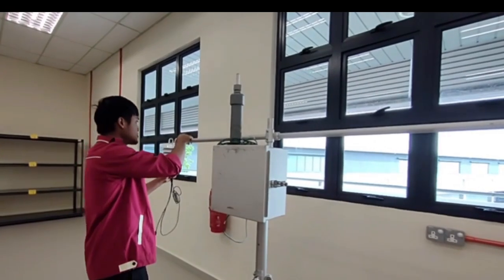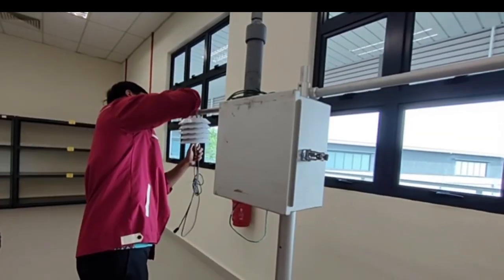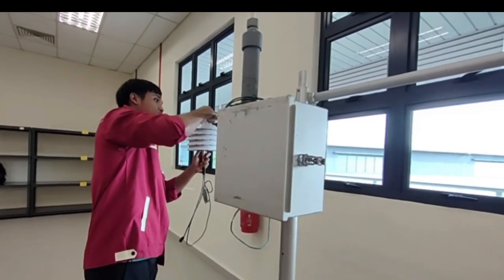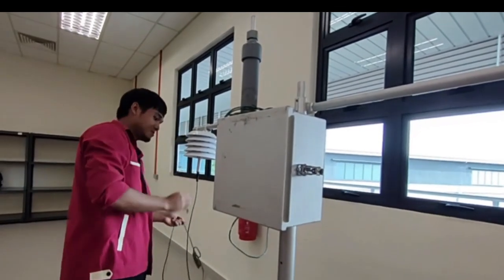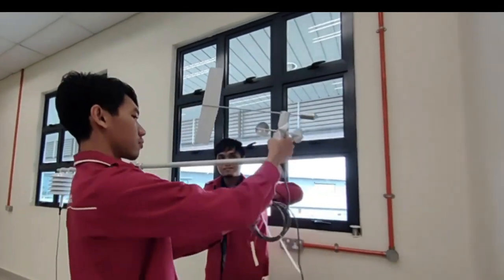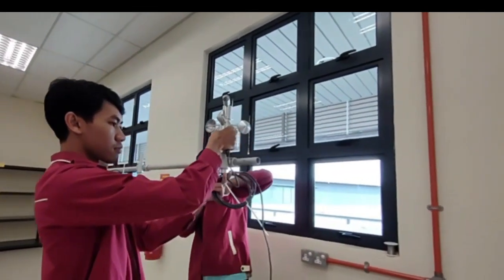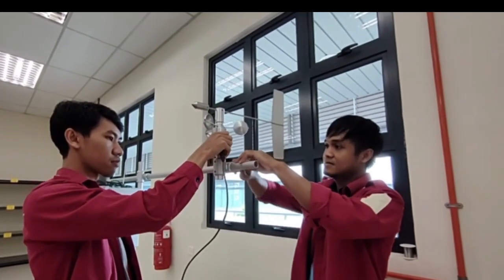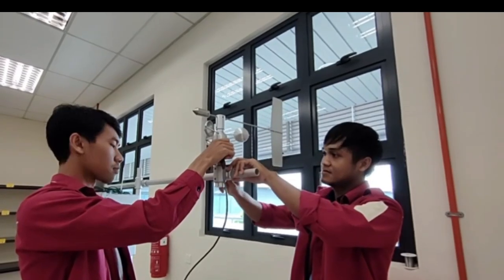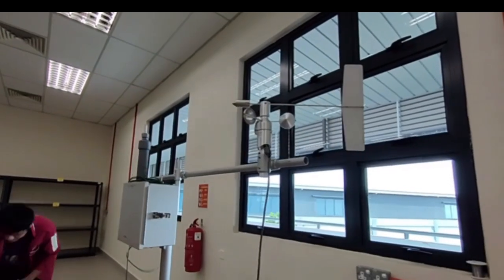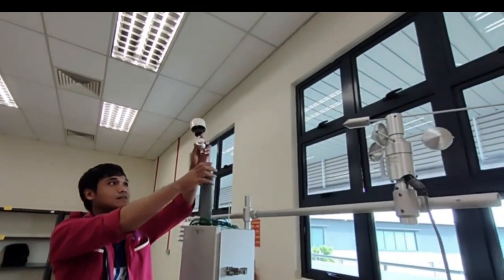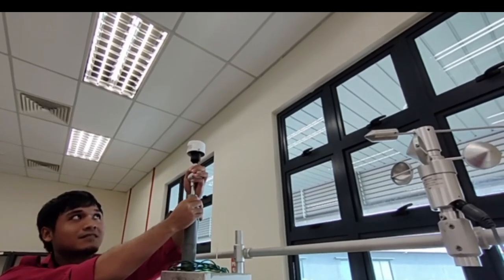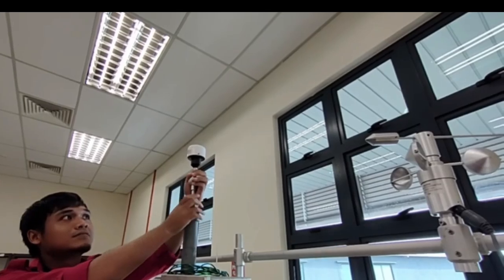Next, the relative humidity sensor was attached at one end of the pole and locked by clipping it. The wind sensor was then attached at the other end of the pole and the nut on the bolt was tightened. The TSP cap was affixed to the PM10 sharp cut cyclone, and then the PM10 sharp cut cyclone was affixed to the inlet of the E-sampler.